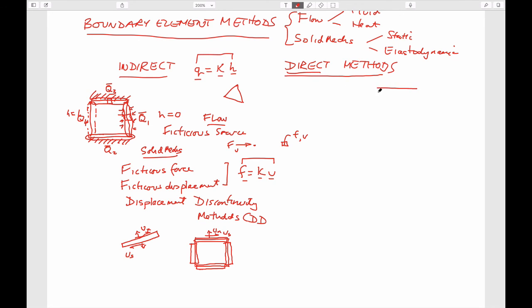So for those, again, you have a geometry, but you set up a system of equations which would give you, for the flow problem, something like a matrix of known terms multiplied by flow velocities, Q, and a matrix of known terms multiplied by the boundary conditions, V. You know every single component in these H and Q matrices because they're just geometric relationships, and it allows you to solve then for the appropriate boundary conditions on that.